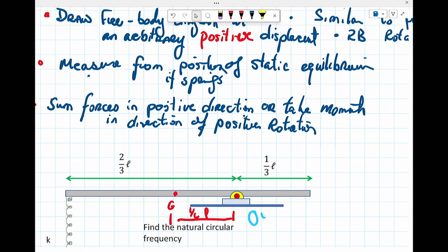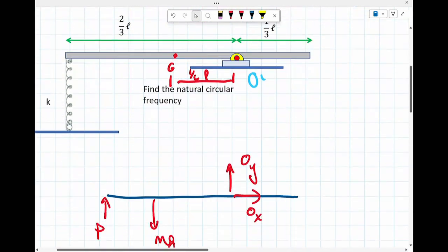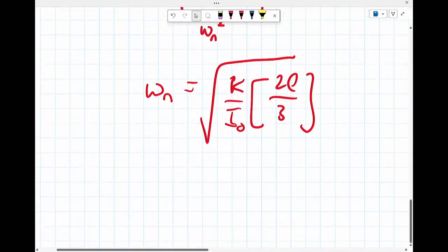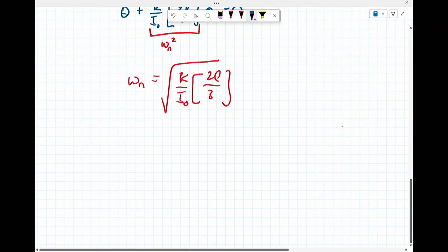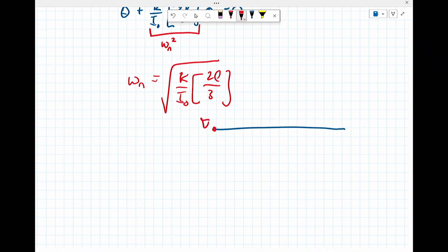In this case, because we canceled out the static friction, theta would be the angular difference from the equilibrium position that's already displaced from the horizontal. So my zero position is not horizontal. It's not here, it's going to be down here. And theta would be the difference between that and any new position. Then the rotation or the vibration occurs here. So this is how you're setting up your equations.